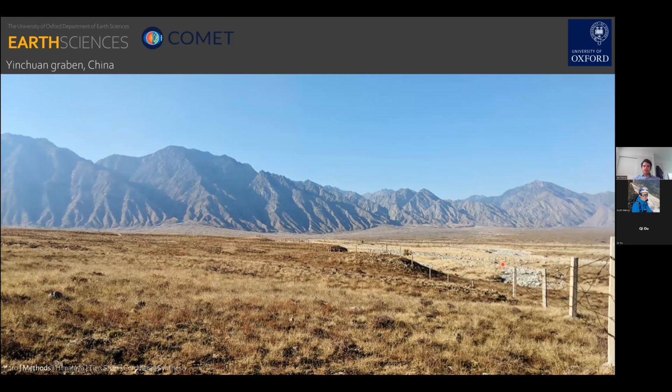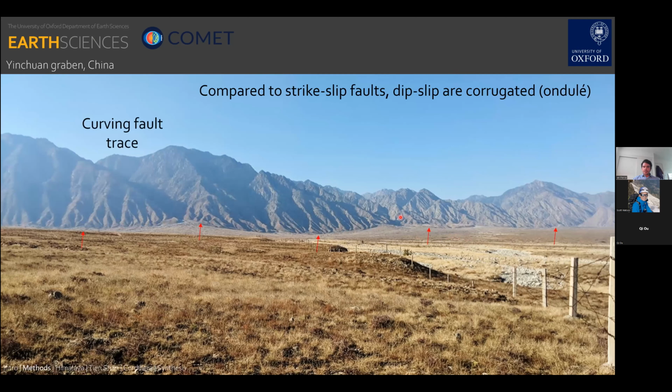Common geomorphic characteristics of dipping faults include more curving, bending fault traces compared to strike-slip faults, steep, abrupt range fronts separating basins from mountains, triangular-shaped facets along a range with deeply incised narrow canyons between them, and uplifted fan remnants that preserve evidence of recent earthquakes.